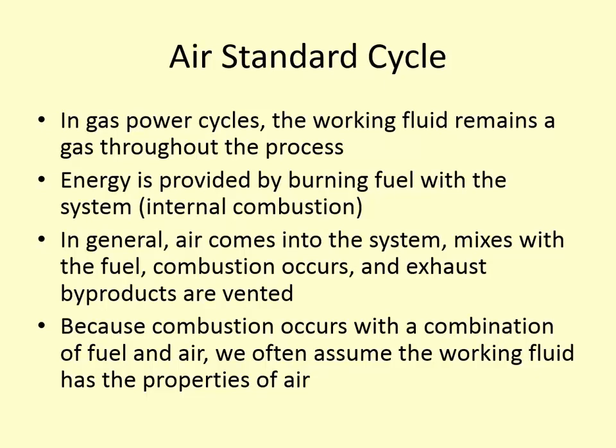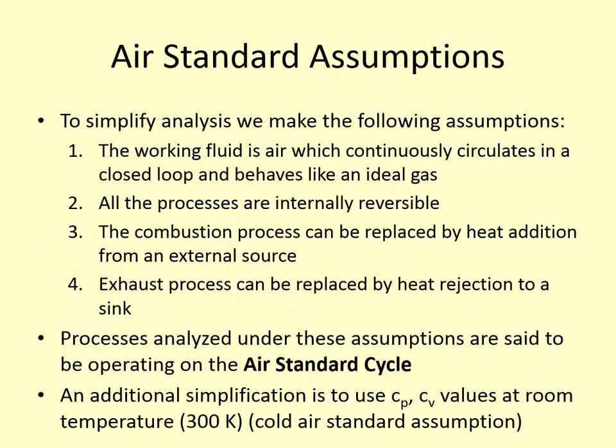And so rather than needing to know the exact fuel to air ratio, or the byproduct of combustion, or the chemistry involved to determine what's actually still being vented or still contained, which hasn't been combusted completely, we just assume that it's air. Okay, so this again simplifies the process, makes it easier to analyze. So we just use the properties of air, which is an ideal gas, in order to analyze these cycles.